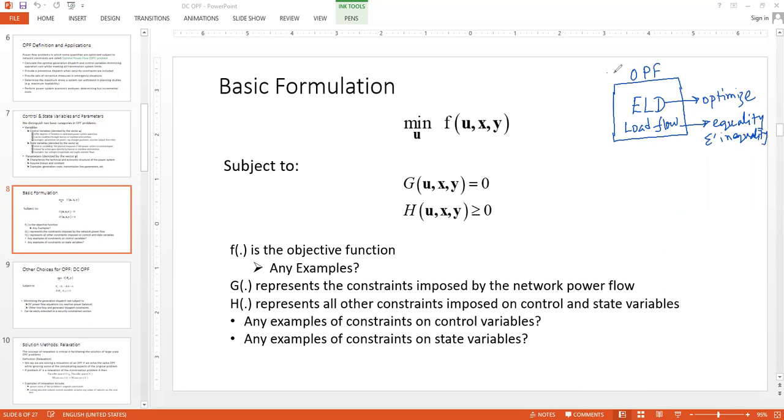By convention, we usually take the help of AC load flow analysis. So this term AC OPF means here the load flow is conducted with the help of the AC power flow. By that we mean, as we have already learned earlier, different algorithms like the Newton-Raphson algorithm or the Gauss-Seidel algorithm or the fast decoupled load flow algorithm. When we adopt those for solving OPF, optimal power flow, then we will call it the AC OPF.